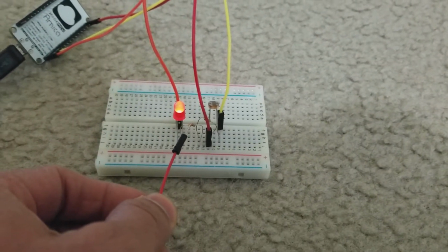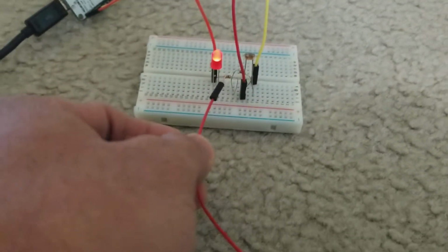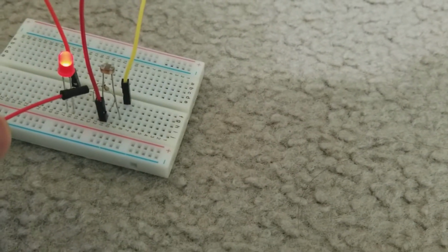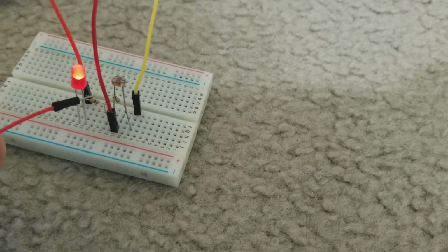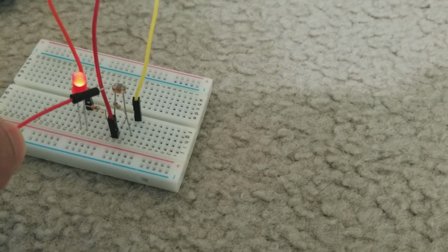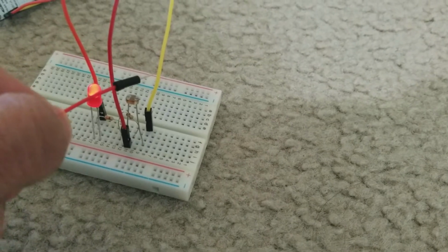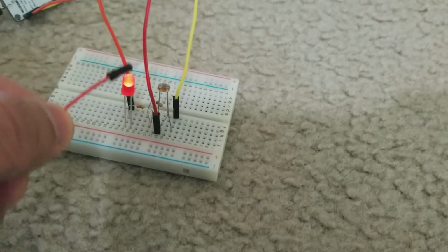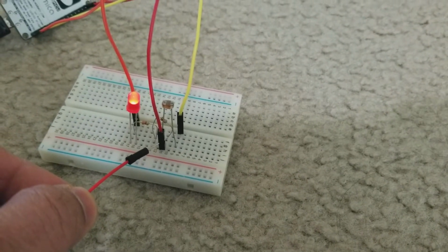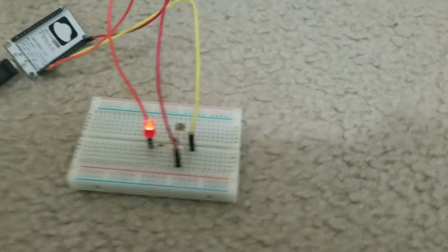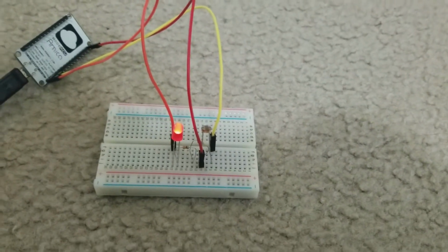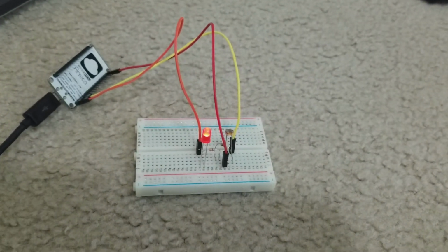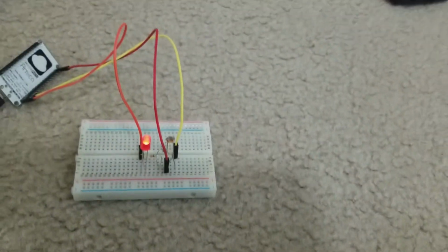This is a 300 ohm resistor, the next in series, and then the next in series again is a 10 kilo ohm resistor, and then we have a photoresistor here, and then the yellow line is the ground, and this sort of reddish line is the signal where I'm picking it up. So basically what you'll observe here is, as I am obstructing the light falling on the photoresistor, you'll see the light intensity changing.